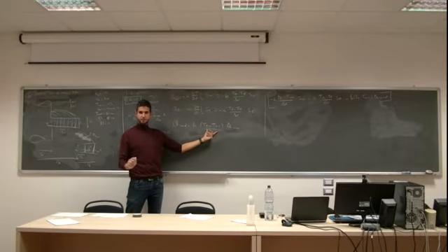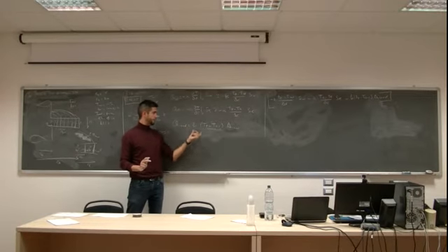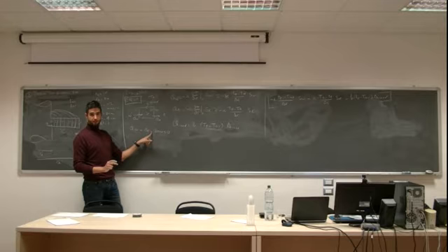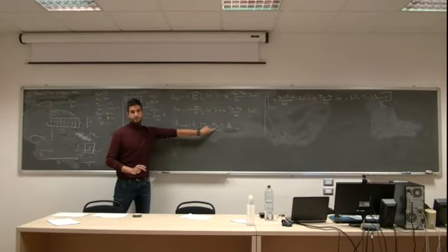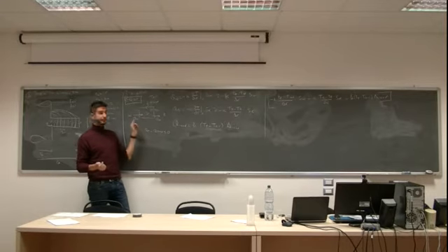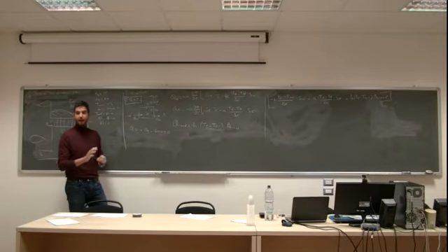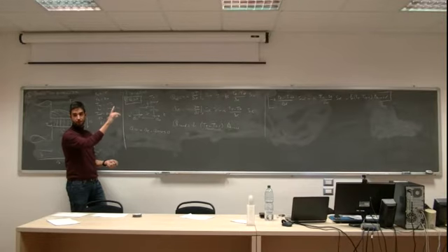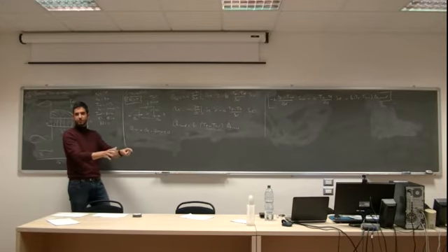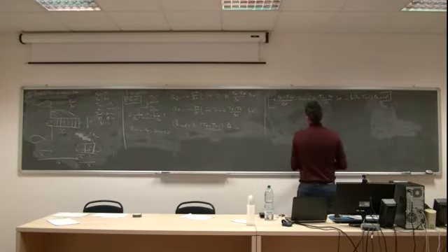Now, if it's the other way around, no worries. It will converge and it will give these negative values. But if you put a negative here, don't flip signs here. The same with convection. You can do whatever you like in the direction, the definitions. I always assume, I don't care about the problem, that flow is going from left to right and from down to up. Always. Then values become negative if they are negative. Okay? Good.